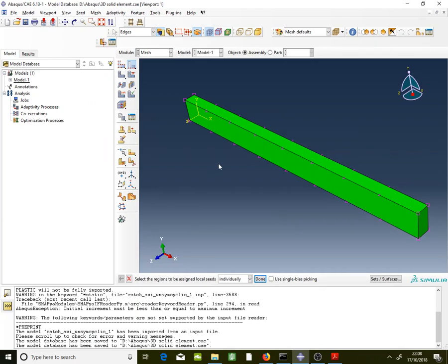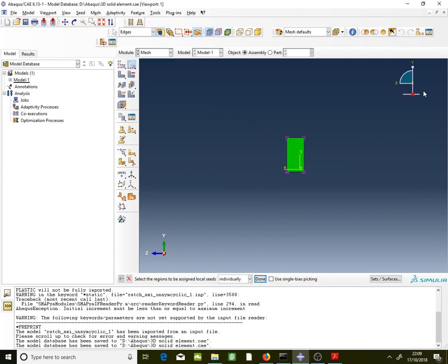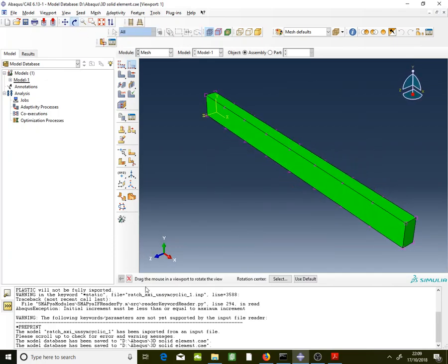An easy way is, instead of collecting each edge 1, 2, 3, 4 somewhere, we could collect them differently simply by pressing on this axis X. You will notice that it rotates. So let's rotate it back and cancel the procedure.